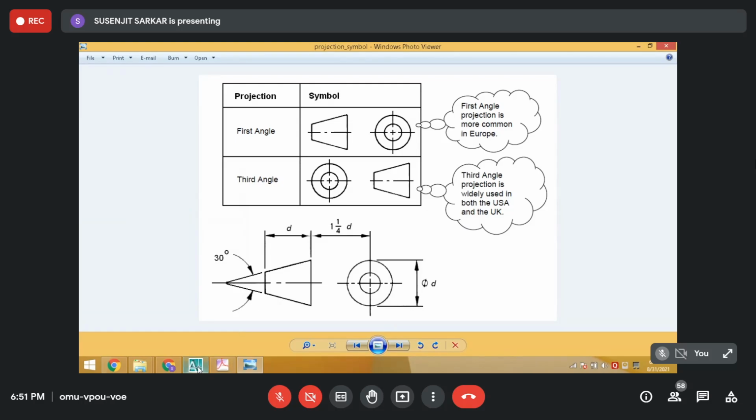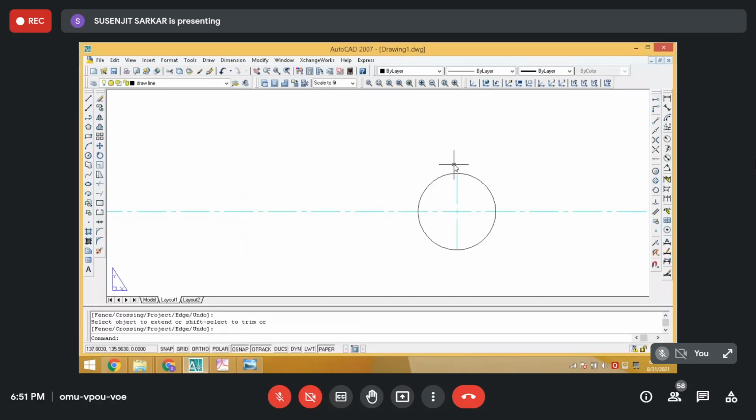So I have to take a distance of 12.5 from here, at the intersection, with snap on. This is at 180 degree angle. If I draw it with ortho vertical, it will look like that.